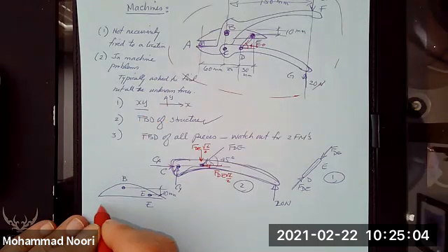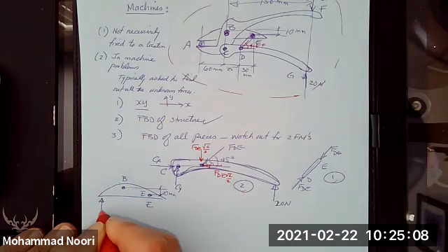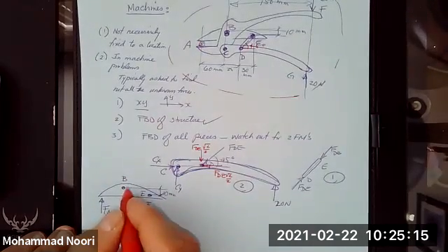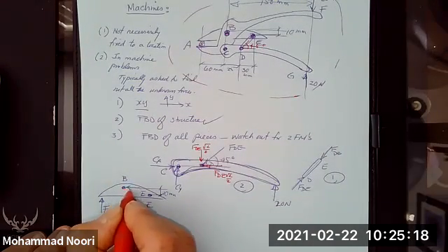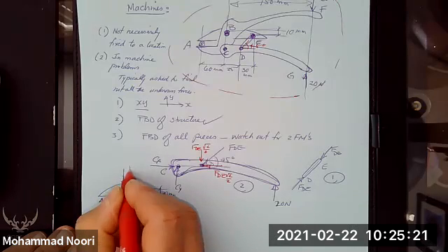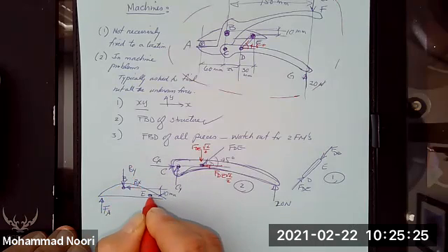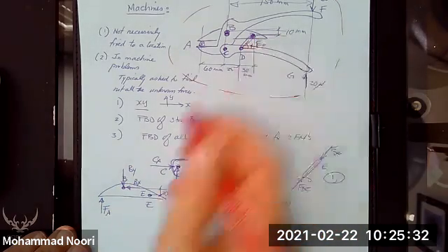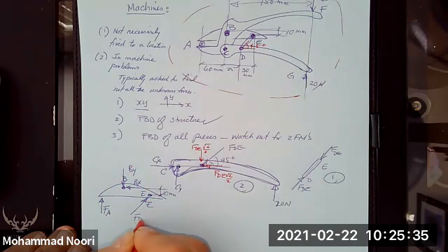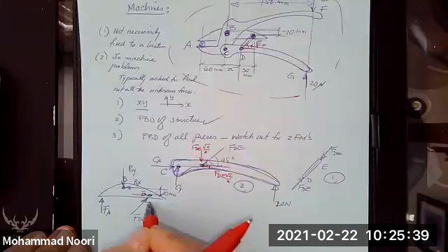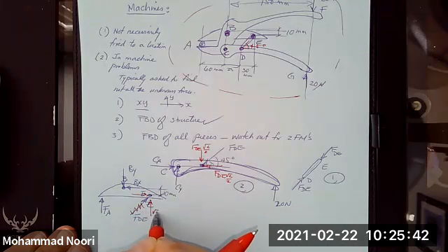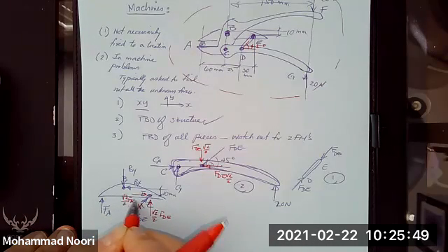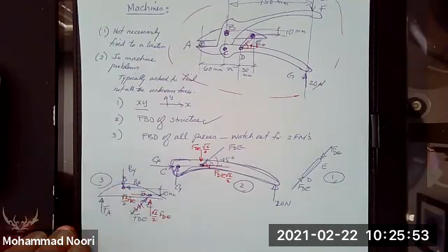This branch, let's assume, is frictionless and acts like a roller. So there is a vertical force that is generated here. And at point B, let's say the two unknown forces are going to be like this, By, Bx, and obviously at point E, you have the force coming from here. So that would be the force of dE. You have resolved that, of course, into its components: square root 2 over 2 F dE, square root 2 over 2 F dE. So that's the free body diagram of the blade.